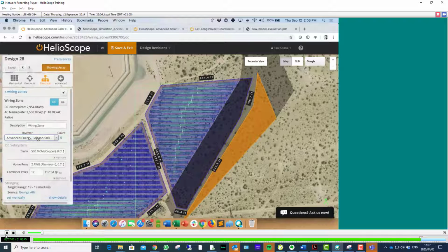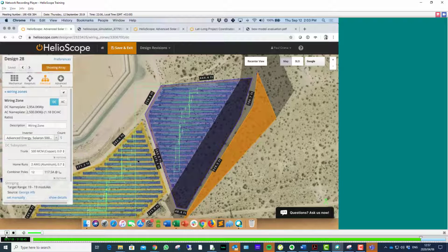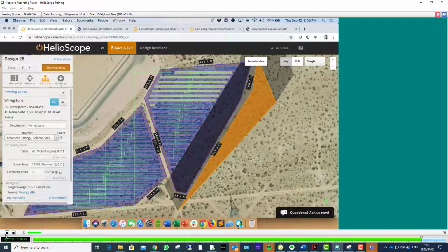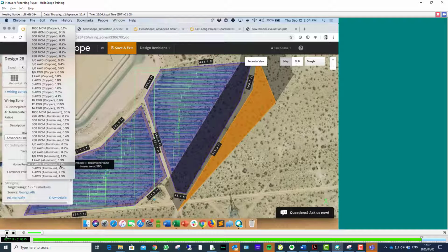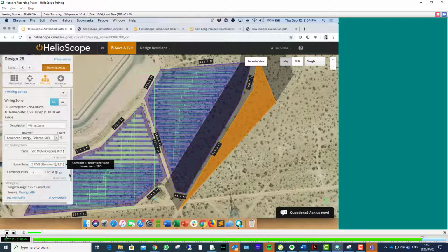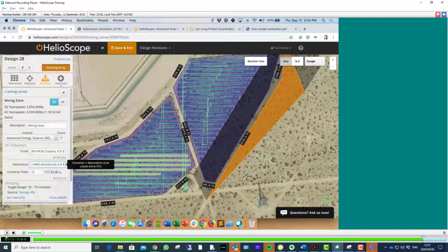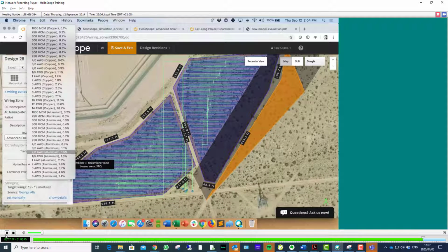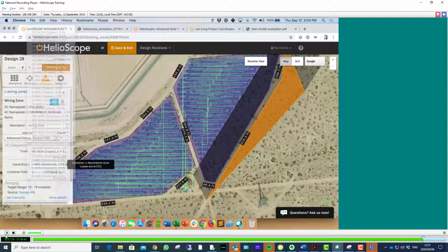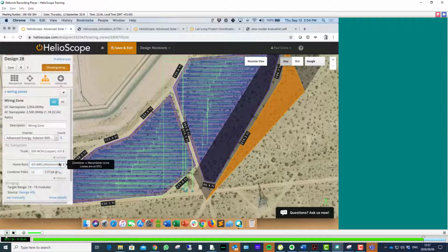If I go up to 500 kilowatt inverters, 5 of that 500K is a 2.5 megawatt AC. And then finally, as I move the inverters around, notice this number, that's 1.7%. That's my voltage drop given the current design. As I move these inverters around, that 1.7 goes to 2.2, then 2.4, then 2.9, which then I might say, okay, let me upsize the wires to a 4-aught aluminum to keep my voltage drop, at this point, 0.9%.